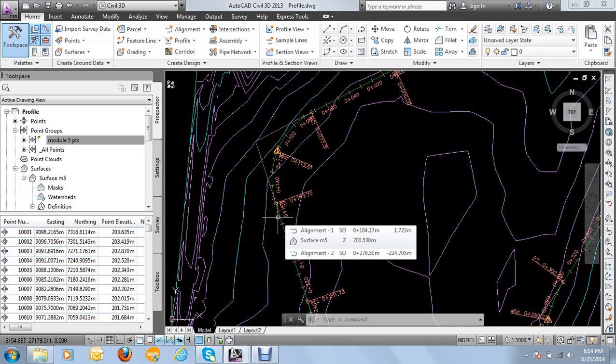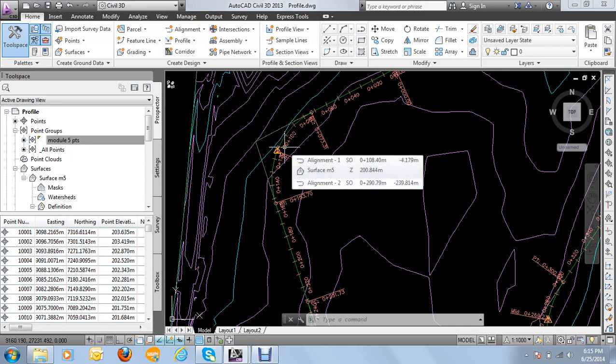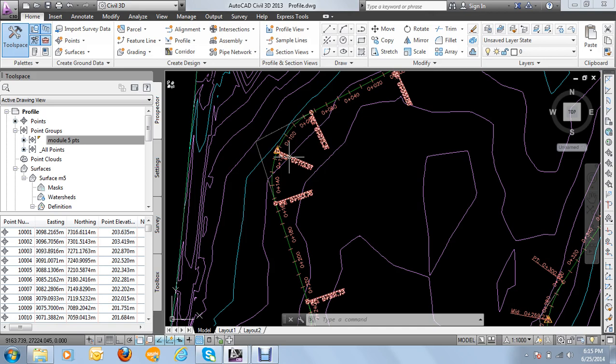You can run Superelevation, because in Superelevation we specifically designed it in order to counter check our curves, specifically the curves where mostly there are some issues. When you check the curves and run superelevation, it's where you can change the radius. You can change the radius, you can change speed, but when you are having an alignment, you only change speed.